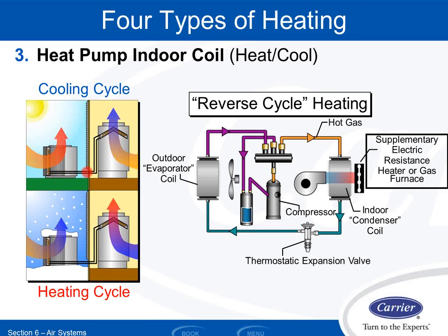So the first thing to understand is that we're not making the air cold. I mean, we are, but that's not really what we're doing. What we're doing is we're extracting the heat out of the air, right? I'm moving the heat out of the air and I'm dumping it outside into your yard. So you're bringing 75, 80 degree air into this system. I'm extracting the heat out of it, which means you're getting 55 degrees coming back into your house. And I'm taking that heat out, running it through the refrigerant lines, and dumping it to the outside.